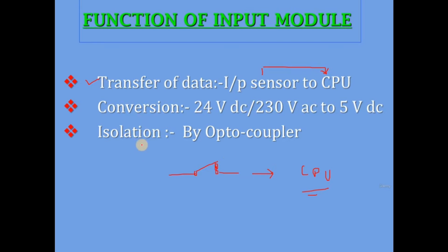And the most important thing is the converter, right? If you don't have a DC power supply, and as we know our requirement is a 24 volt DC power supply, then simply we can go with the SMPS. This SMPS will fulfill the requirement of our DC power supply.